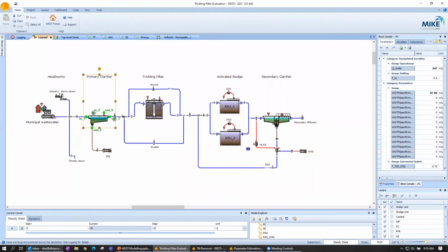Because we skim grease and soaps from the top of the clarifier, and usually it makes its way into the primary sludge. Maybe it's a really small stream, 100 gallons per day or something like that, and we're treating 10 million gallons per day. So it might not be hydraulically relevant.